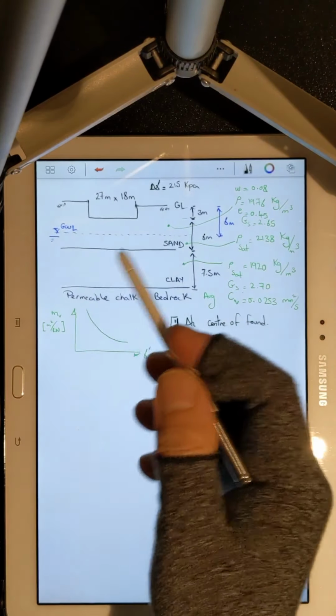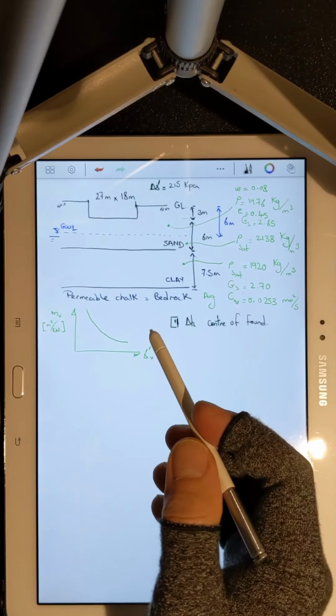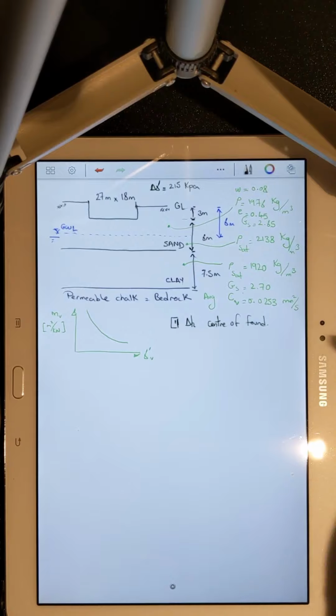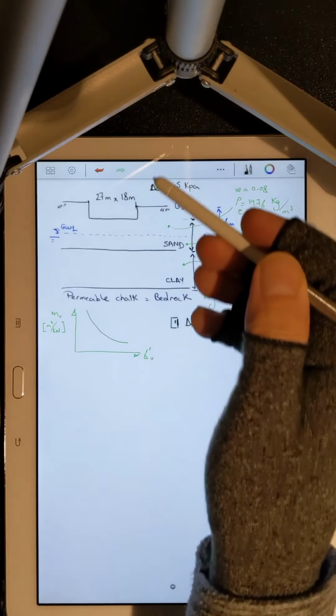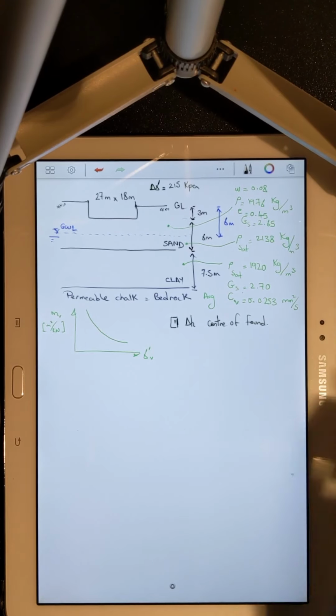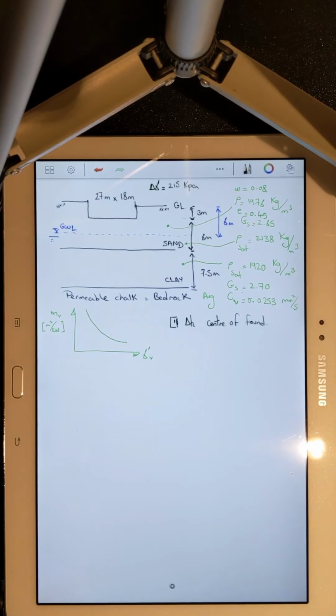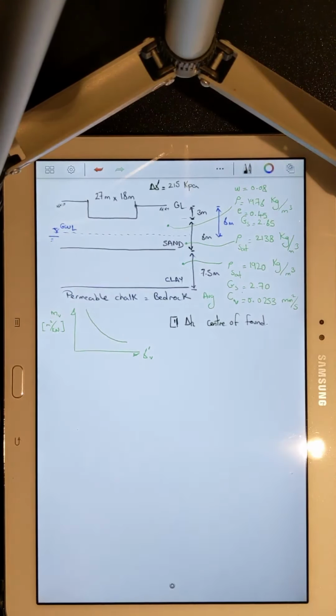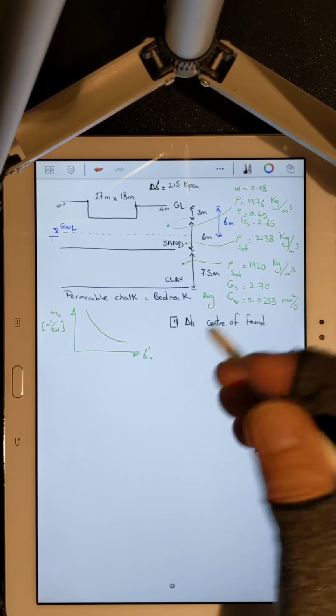Right, by looking into this question, you can see that you have some data which is coming from the oedometer test, but you do not have the variation of void ratio versus log sigma dash. And for that reason, you cannot say whether your soil is over-consolidated or normally consolidated. By soil, I mean clay, because sand does not have much consolidation, we ignore that.